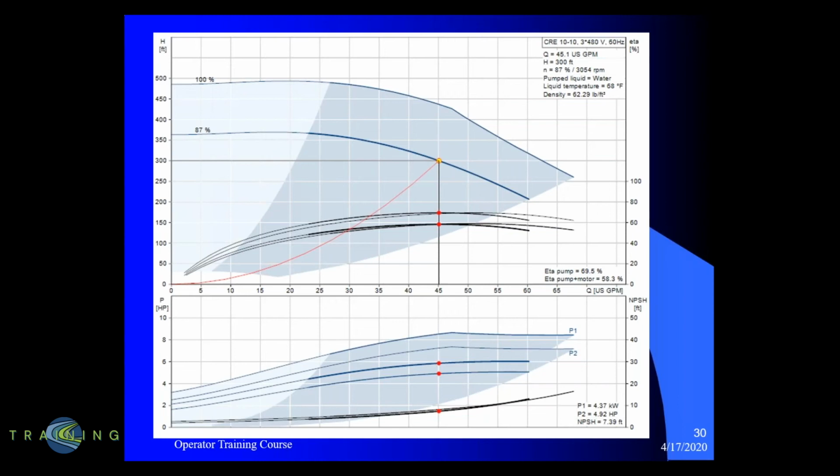And when that happens, you get one little piece thick and another piece thick, and it starts clogging that up. So yes, you're right. The most inefficient thing about a sewage pump is not just that they have to pass solids. It's that sometimes they get so clogged up that they can't pass any, and that's a problem. And it's the hardest thing for a sewage system to operate in is trying to make sure that those pumps don't clog.